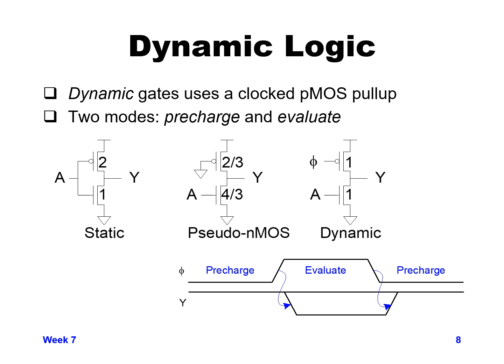But for pseudo NMOS, we're still not going to get all the way to ground, and we have the static current always being drawn when we're evaluating. In a dynamic gate, we now only have a size 1 NMOS there, because we're planning on only having the value of A go high when the PMOS device is off.